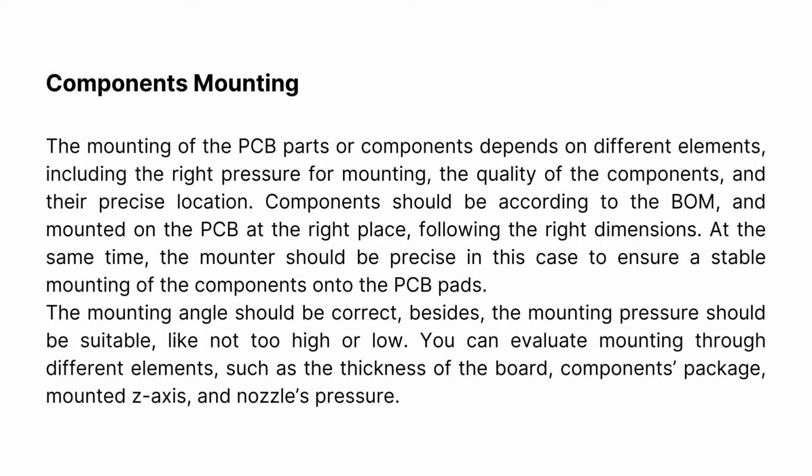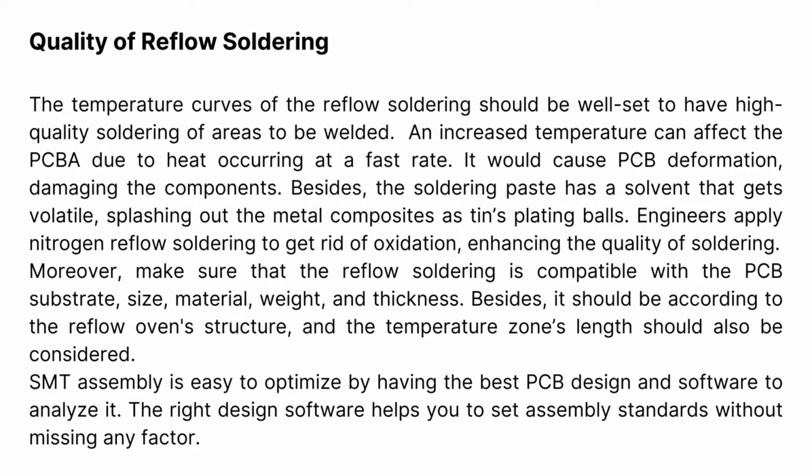Components should be according to the BOM, and mounted on the PCB at the right place, following the right dimensions. At the same time, the mounter should be precise in this case to ensure a stable mounting of the components onto the PCB pads. The mounting angle should be correct. Besides, the mounting pressure should be suitable, like not too high or low. You can evaluate mounting through different elements, such as the thickness of the board, components package, mounted Z-axis, and nozzles pressure.